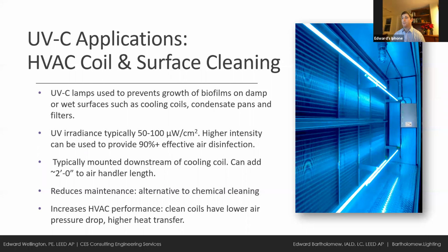It also decreases the fan energy required to push the air through the coil and increases the coil heat transfer performance. Actually, a study done in Florida after they installed this system, it cleaned the coils so well that the air pressure drop decreased by over 20%, and heat transfer increased by 15%.